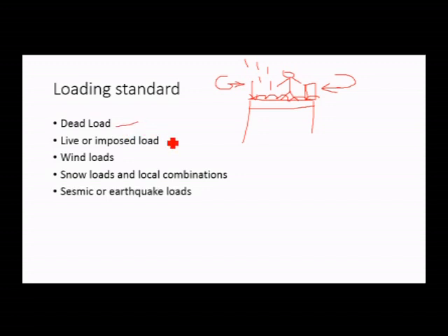Dead load will comprise the self weight of the material that is used in construction, such as brick, stone, concrete, wood and other various materials. The unit weight of most of the commonly used materials are specified in the Indian National Standard Code IS 875, 1987.